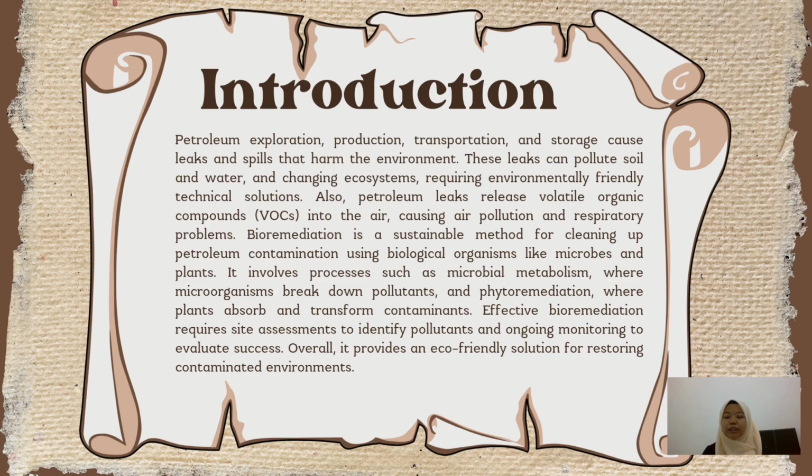One of the methods that can be used is bioremediation. Bioremediation is a sustainable method for cleaning up petroleum contamination using biological organisms like microbes and plants. It involves processes such as microbial metabolism, where microorganisms break down pollutants, and phytoremediation, where plants absorb and transport contaminants. Effective bioremediation requires site assessment to identify pollutants and ongoing monitoring to evaluate success. Overall, it provides an eco-friendly solution for restoring contaminated environments.